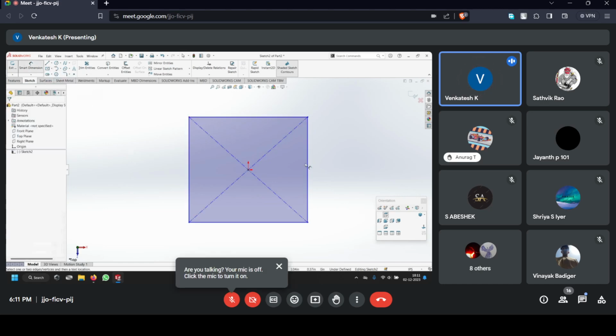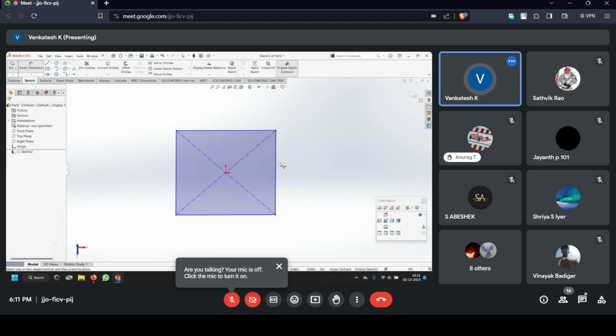Now, the first thing we decide is, we normally do this design based on the measurements which we get by measuring a person, meaning the driver. It is always based on the driver. The design of the chassis is mostly based on the driver. After getting these certain measurements, it is normally done by the driver sitting on the floor in our lab itself, and we use a duct tape to get all the members.